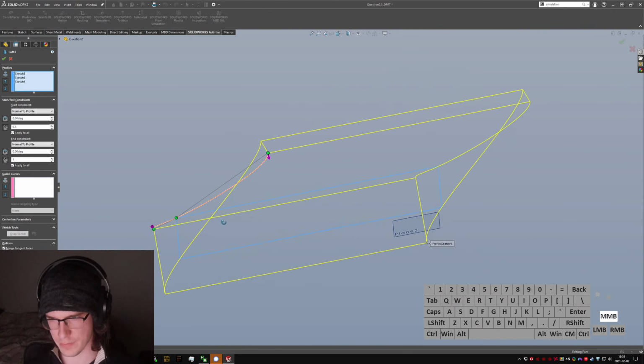And the other thing is, just be willing to fiddle with the numbers. This profile is obviously not perpendicular to the flow, it would be more sort of come to this angle. Hide this plane. Whoops, nope, don't do a new sketch, please. Just hide that plane. So we've got this sketch here. It's difficult to make it perpendicular to the flow and have an axis that it's parallel with right here. I could do that with a sketch. I could add another line in this sketch and say, just have it be, say, 8 inches over this way, and use that as a control axis, or one of the things that this plane is parallel to.